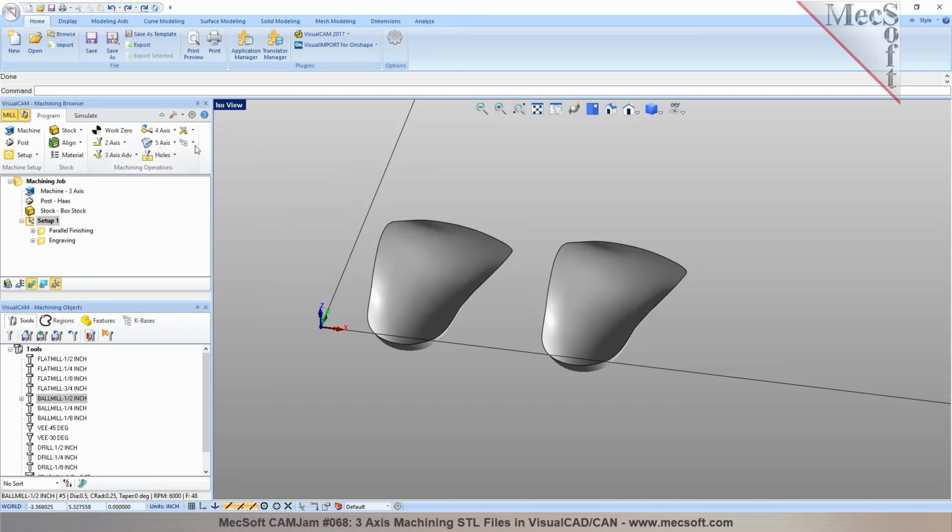You just load the knowledge base and associate the machining regions to it. We can also automate the selection of machining regions by doing boundary selections, where you can pick all the curves on a certain layer. We can do automation on it.